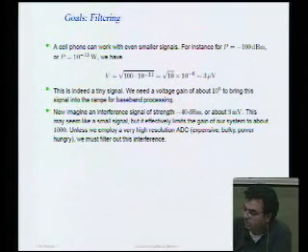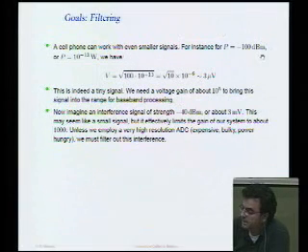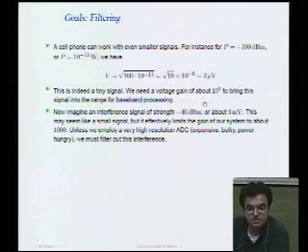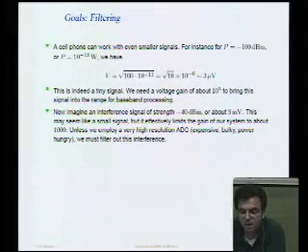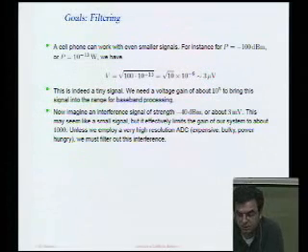Now the other point about communication is that while you're receiving, in that near-far situation that we described, while you're receiving this tiny signal, let's say you're also receiving another signal, which is an interference that's minus 40 dBm. Now again, that's only about 3 millivolts. That's a pretty small signal, right? Nothing to worry about, especially when we look at distortion and large signal behavior of transistors. Yeah, 3 millivolts is a pretty reasonably small signal.